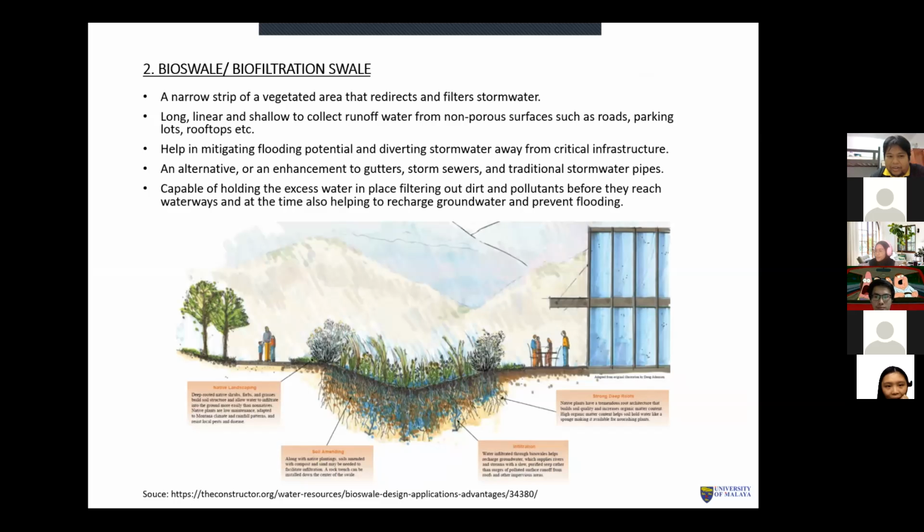Actually, Nicole, you can apply this very easily on the two slopes, the south and north facing slopes. I showed you the north facing slope just now, facing engineering. You can have bioswales there to stop water from going down. Right now it's like a waterfall. And then the south facing one, facing college 6, again, you can implement there. And that one is more accessible. Students can help to plant things and maintain it if they want to. But again, like my earlier suggestion, you have to look beyond proposing. You have to look into how it can be maintained, make it sustainable.